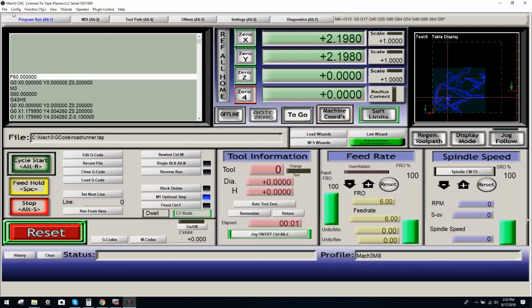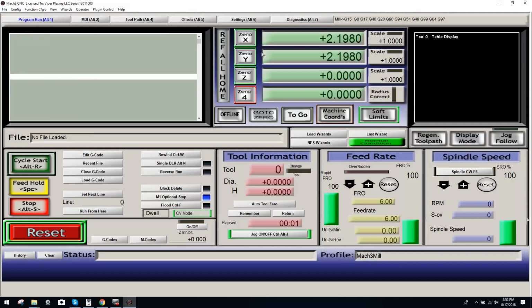Let's say I close out my G code. Now this is something I highly recommend you guys do as far as testing your system, going through a new setup. This is a process I highly recommend. I would actually close the G code after you've jogged arbitrarily on your table. You're going to close it. Once you close it, even though you have no table represented, you know you're off center of your G54. You're not at your start or home position. Okay?